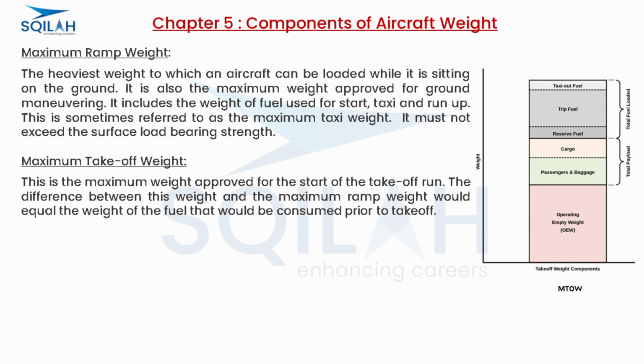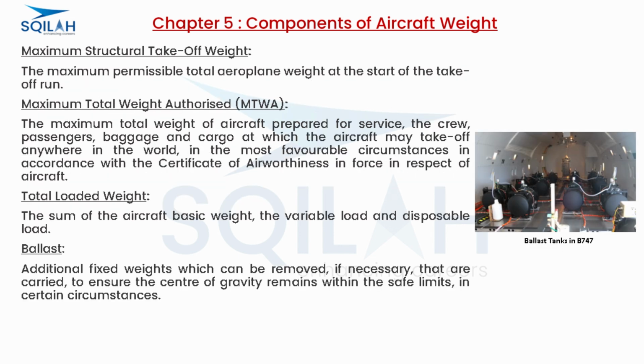Maximum takeoff weight. This is the maximum weight approved for the start of the takeoff run. The difference between this weight and the maximum ramp weight would equal the weight of the fuel that would be consumed prior to takeoff. Maximum structural takeoff weight. The maximum permissible total airplane weight at the start of the takeoff run.